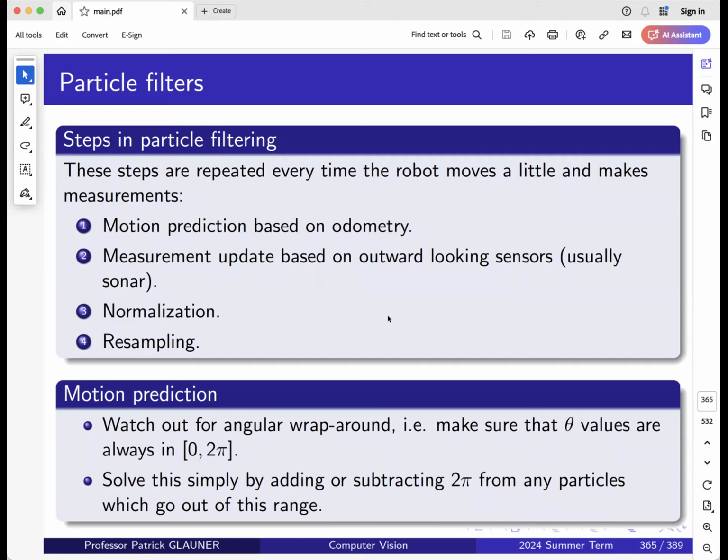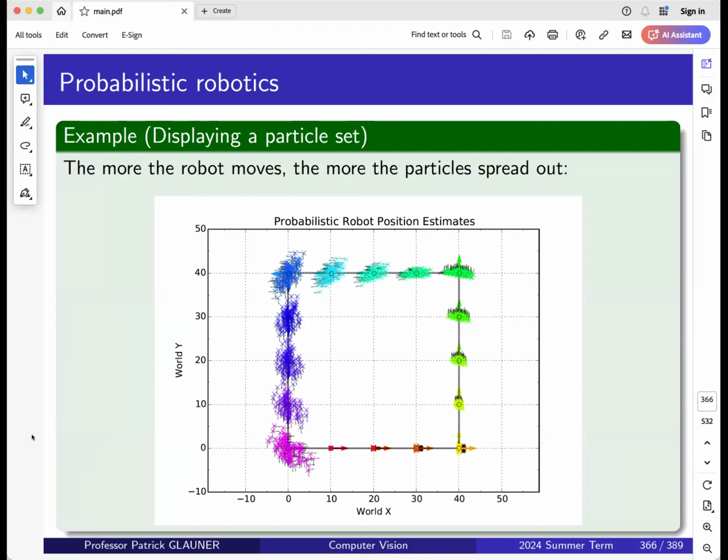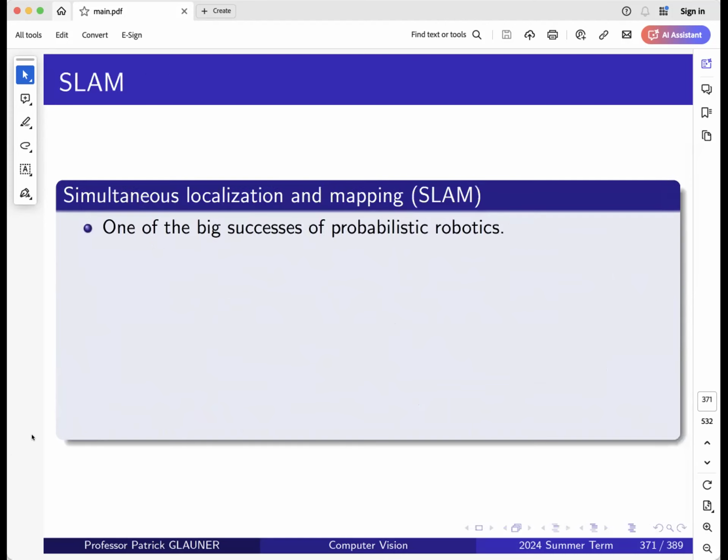In practice, you would often use a particle filter for estimating the robot state, and you would maybe use a Kalman filter for tracking some objects. So if your robot wants to track some other object, maybe for that you would rather be using a Kalman filter then. But they're both two approaches to doing filtering with their own pros and cons.